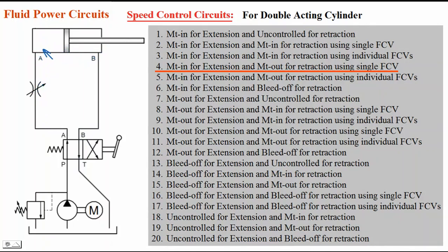That is meter out for retraction. This circuit is metered in for extension and meter out for retraction by using a single flow control valve.